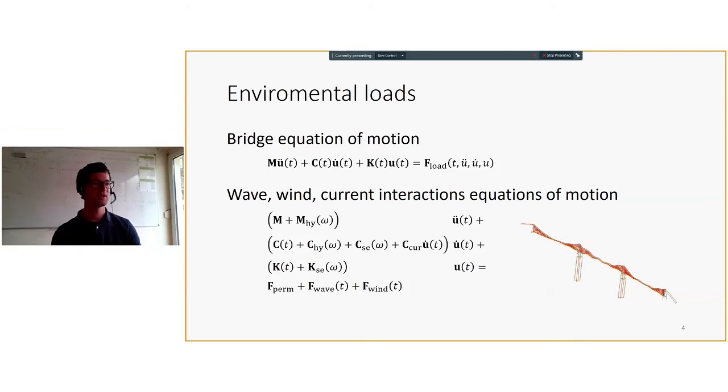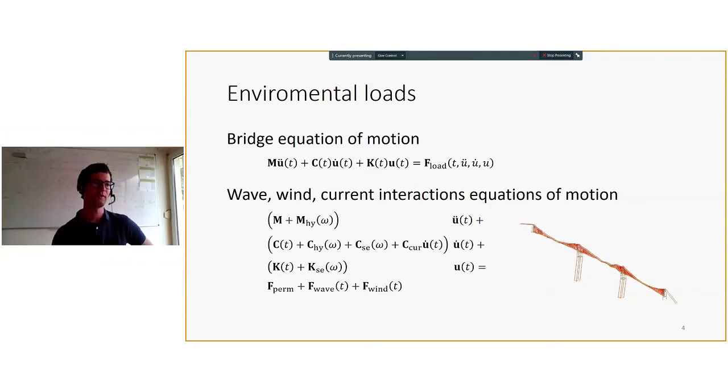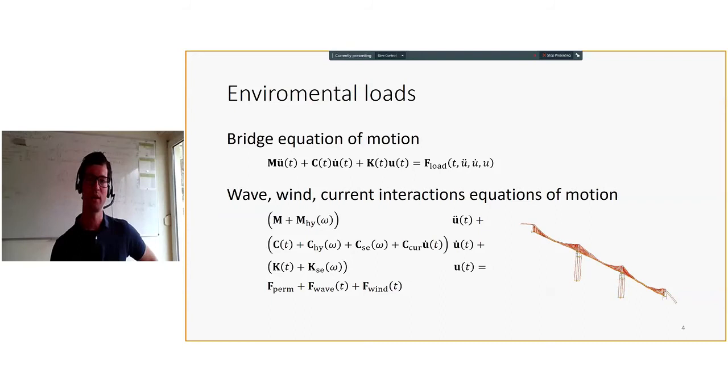And you need to have a proper formulation where you can introduce those effects either on the left-hand side of the dynamic equation as implicit, or you can put it as nonlinear on the right-hand side where you iterate. So the background of this is that we use a Newmark implicit, explicit time integration scheme. And as such, this is then able to resolve these equations.